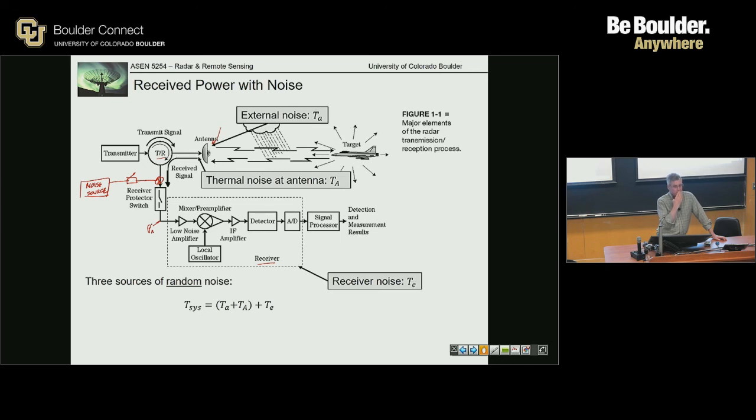Any noise that goes into a passive component generates heat, and the heat in turn generates noise, and it's an energy exchange, so they really don't add more noise. It's really confusing. It adds signal to noise because it attenuates signal, but does not add noise power because the noise power just does an energy exchange. Okay. Any comments on that? Because it confuses the hell out of me.